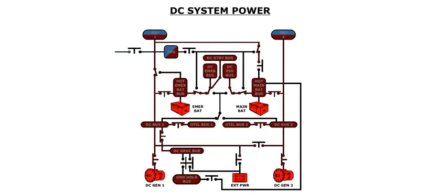The 28-volt DC system is normally powered by 2 engine-driven starter generators, or an external ground power unit. 2 batteries provide a source of power for emergencies, or for when the aircraft is on the ground, without the engines running and no external ground power unit.